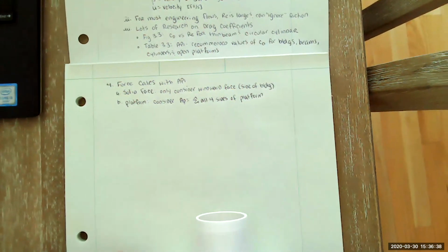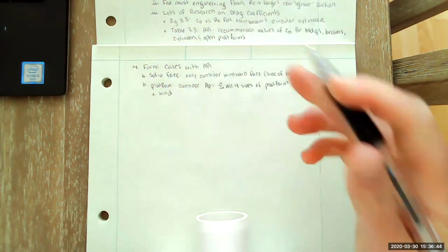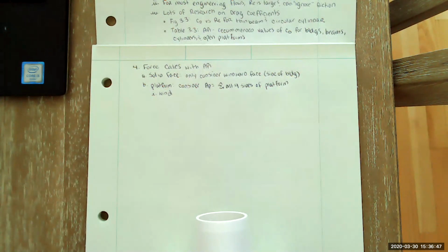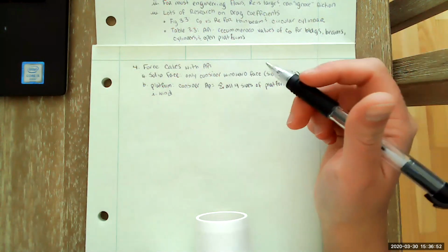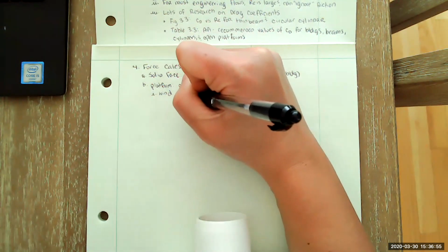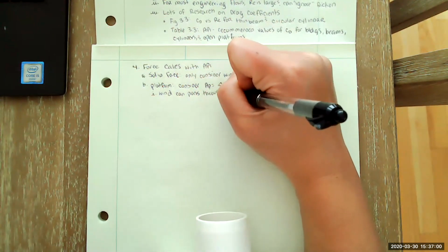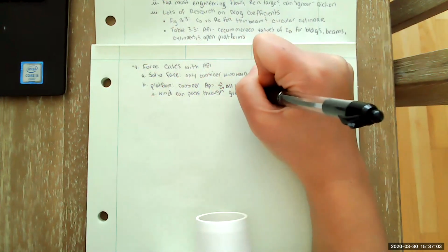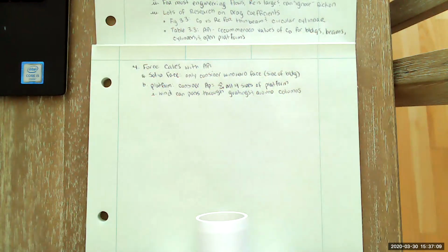And the reason that API does this is because you can have wind that passes through gratings or sort of through gaps in platforms, which typically have a lot of gratings to allow, you know, overwash to wash off, etc. So wind can pass through gratings and around columns. And so using the total sum of all four sides of the projected area is a conservative approach to calculating the projected area.